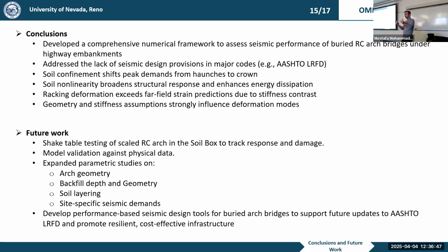By introducing the soil into the structure, we saw those racking displacements were different. One was 5 millimeters, the other one was 1.5 millimeters. And also we saw that the geometry and stiffness assumptions strongly influence deformation.